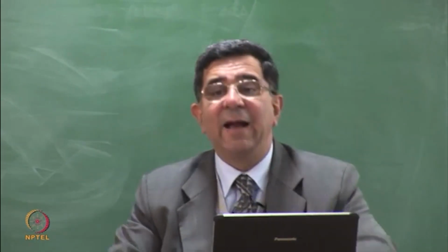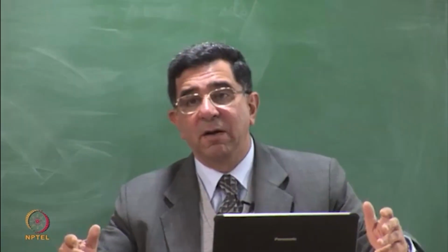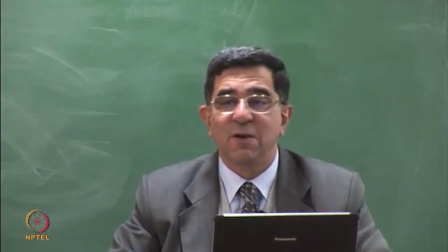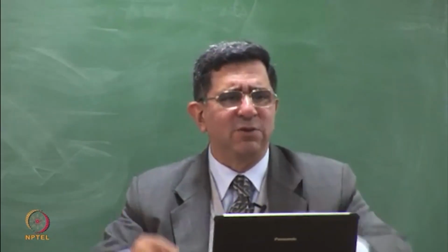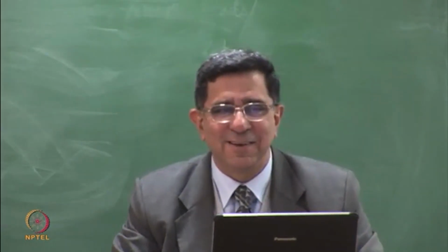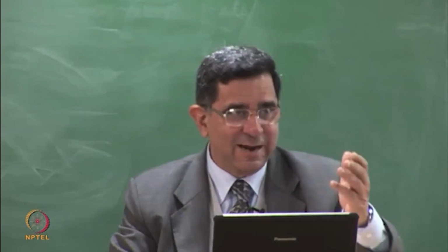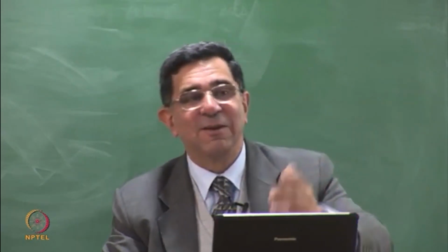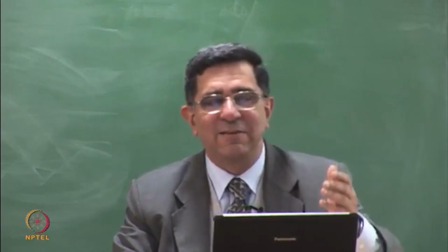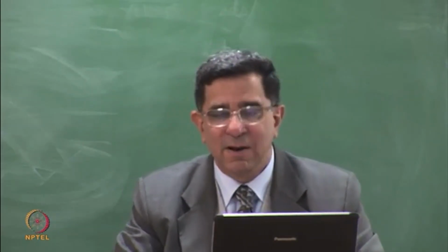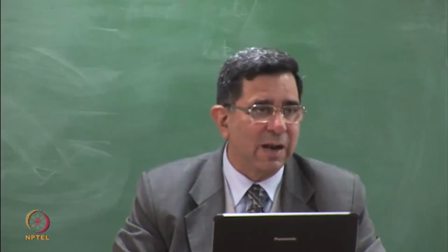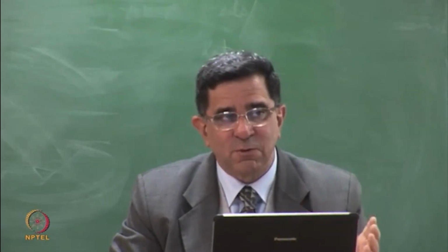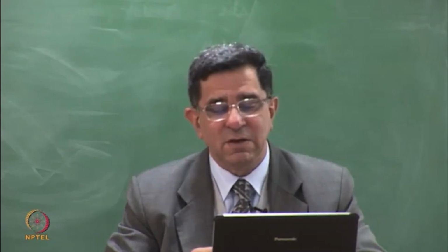It's not that I operate a phase from January to December. A lot of things are governed by financial year. If yours is an academic year, you can always say I'll do it academic year, but financial year means you start the landfill in April and immediately 2 months afterwards or 3 months afterwards you start having a monsoon. Doesn't work well. Close your phases before the monsoons so that you have least amount of leachate.